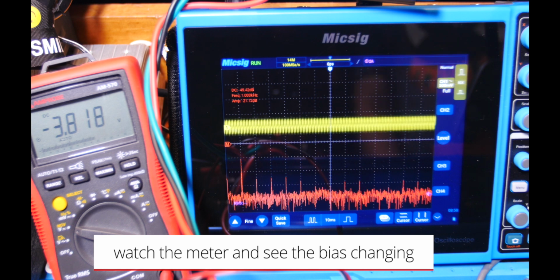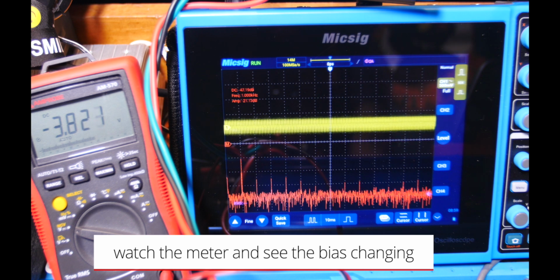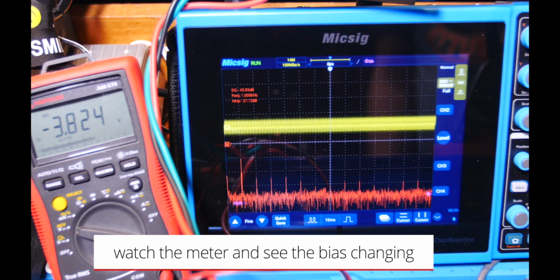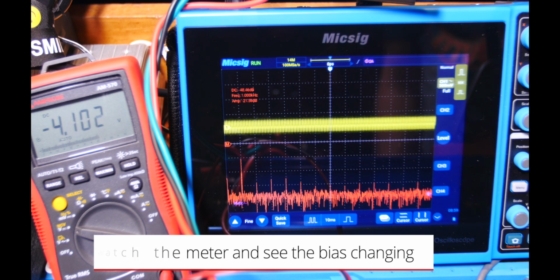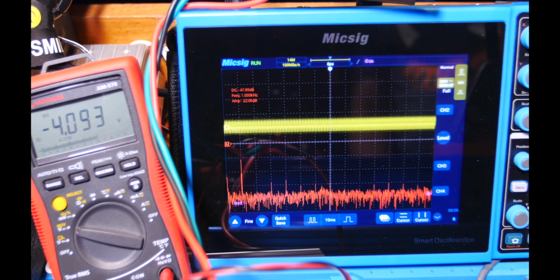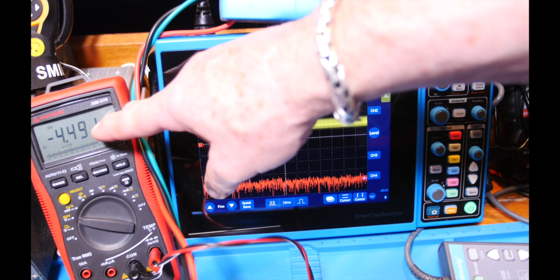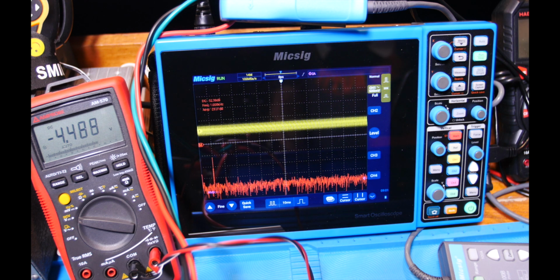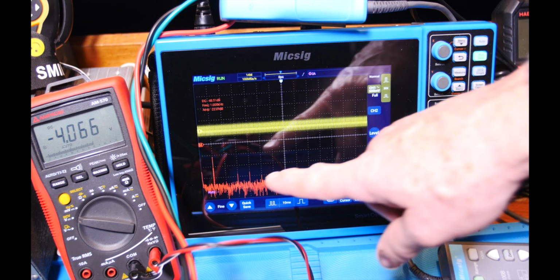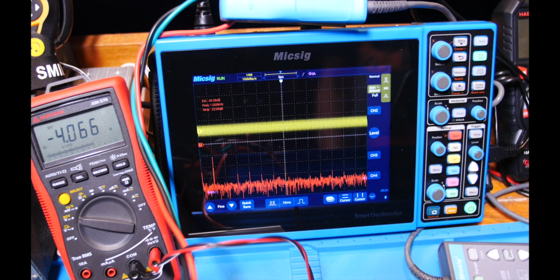That's 1.5 volts at my signal, and I do see that red light coming on the power supply. If I drop it down, right there the light goes off, but I still see some spikes. Something else I notice is this 4.5 volts drops away as I bring my signal up, and the noise starts jumping up, the signal's dropping. So I think it's a play between the power supply not having enough bulk capacitance to supply a nice solid voltage, and we're seeing that.